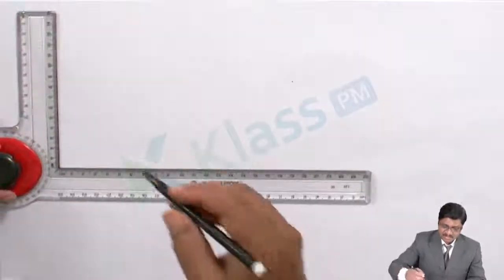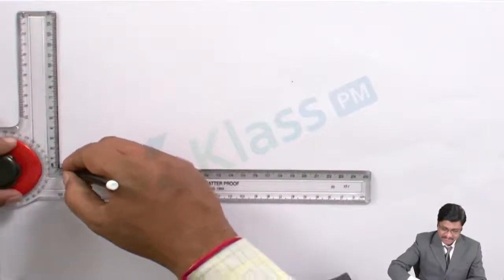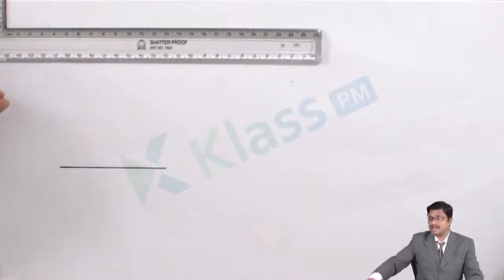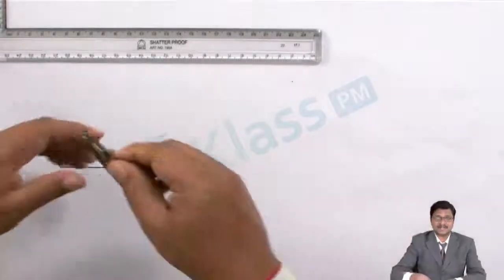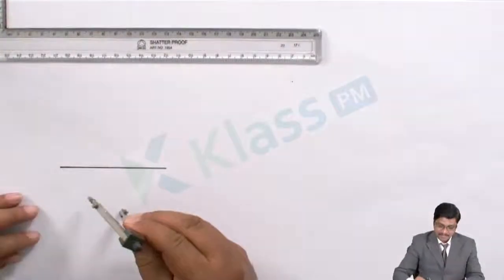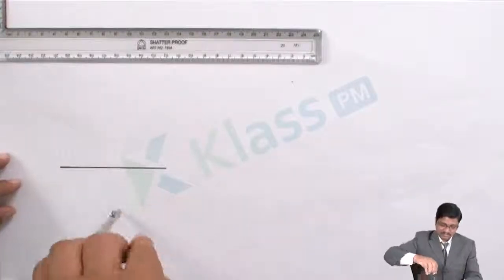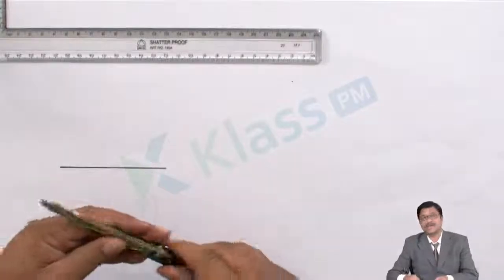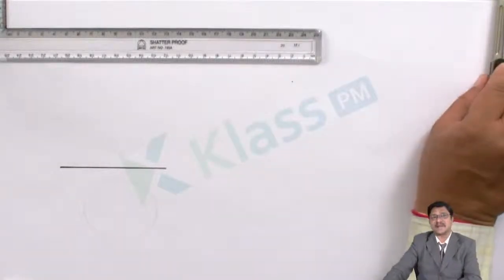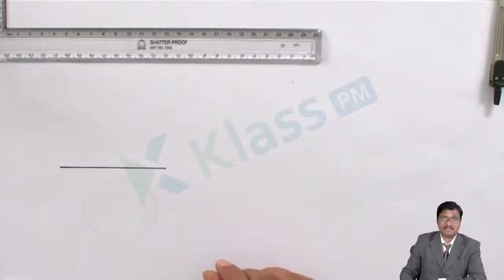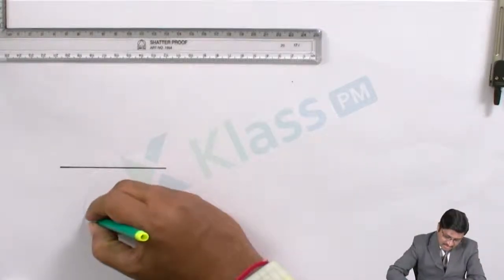First, draw the reference line. Since a cone has been given, draw the cone with the given dimensions. The diameter is 60 mm, so take 30 mm as the radius. Draw the primary circle first, to represent the top view. Whenever the resting condition is not given, you can understand the default position as the standing position. When standing, the base must be in HP, so the top view is taken as our primary view. To make it visible, I am inking the line.